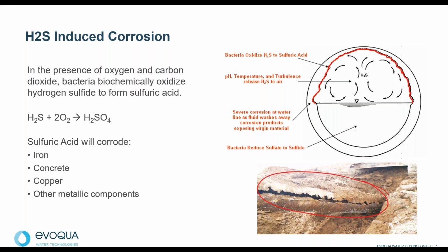The force main pipe pictured was corroded along its center line because of the hydrogen sulfide that ate through the ductile iron piping. These sewer pipes are commonly found underneath roads and other above ground structures. Once these pipes begin to leak, sediment and soil can wash away with the sewage. Prolonged exposure to a leak eventually leads to sinkholes and collapses underneath these roads and structures, resulting in serious infrastructure